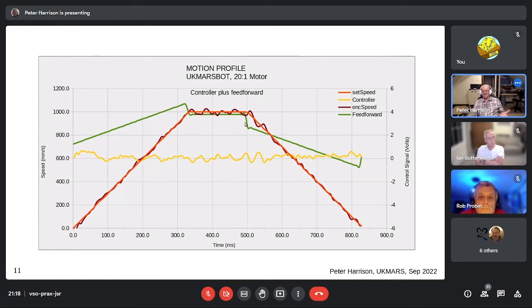It's a poor phraseology, but for lack of a better term, you have to suck current out of the motor, right? You have to have current going in the opposite direction to brake the motor, but nonetheless, it's current. It's accelerating current, decelerating current, so the step is negative and carries on down below 0. Because just before we come to a halt, we're actually trying to get torque in the opposite direction. So the size of this step is determining the amount of accelerating torque that goes in.